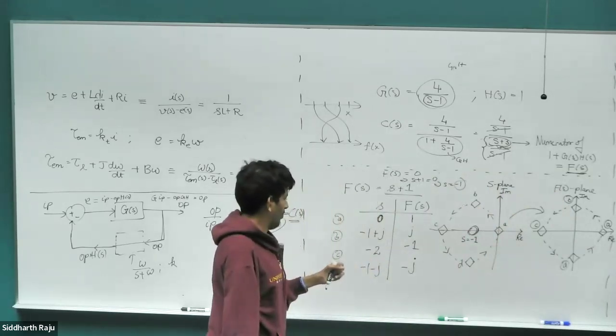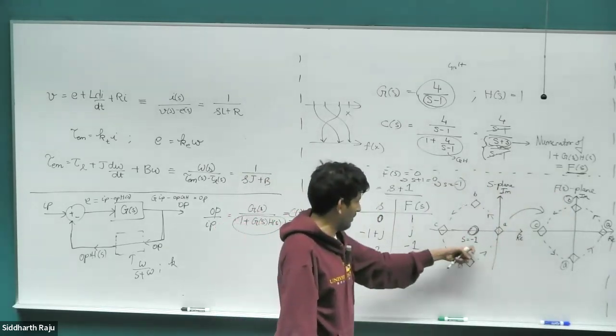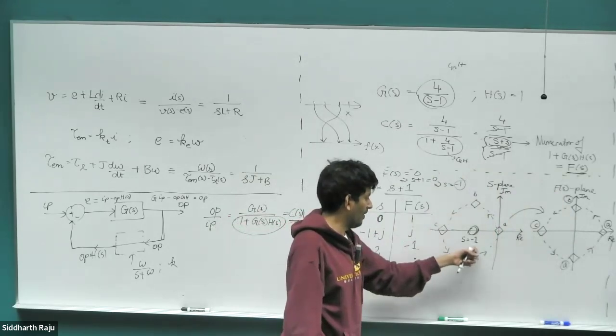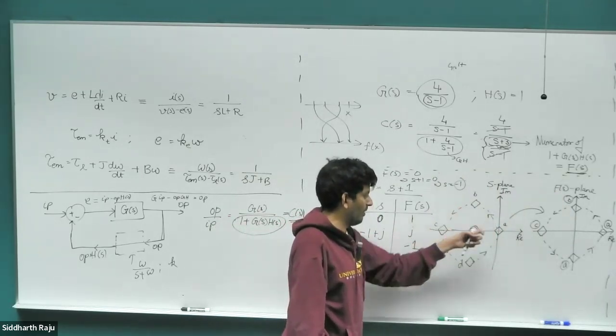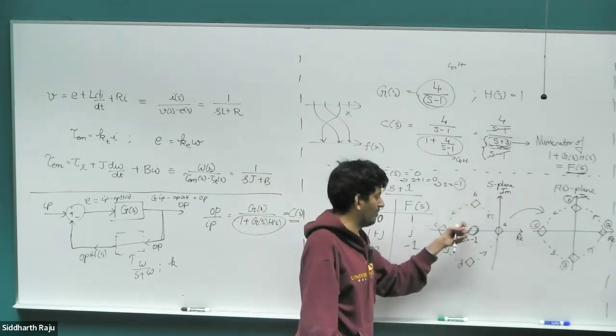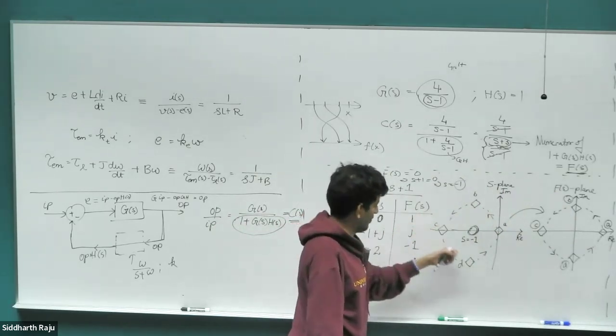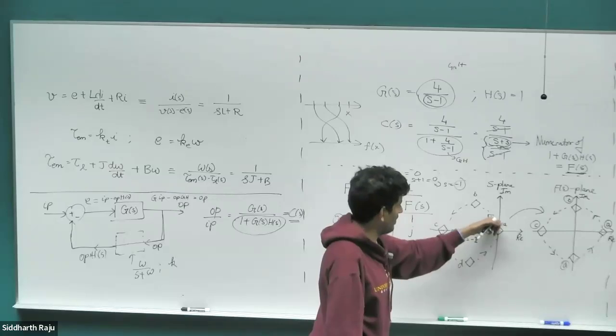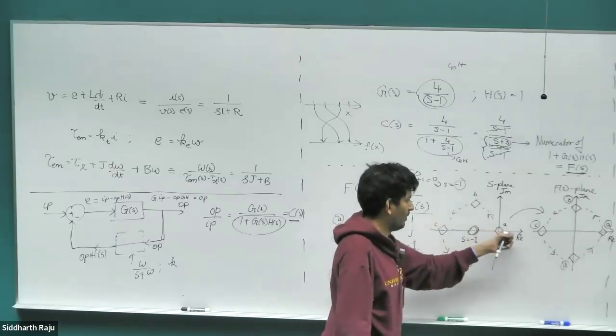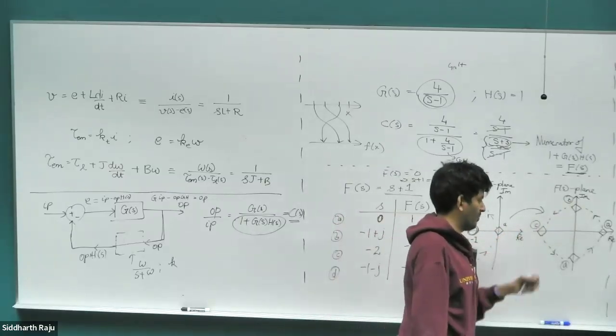Okay. So what we are going to do is, given any zeros, we are going to encircle it with some kind of loop, and then we are going to take some discrete set of points and then figure out what f of s comes out to for those discrete set of points. Just for simplicity, I've taken 4 points surrounding it, but ideally you would want to choose numerous points so that you can get a very good map of where it maps into.